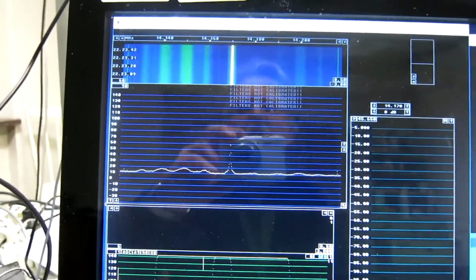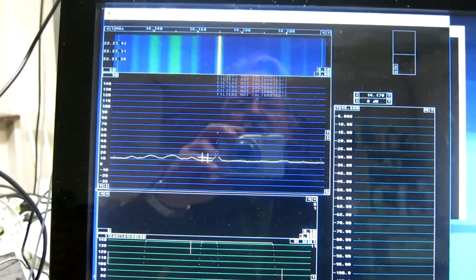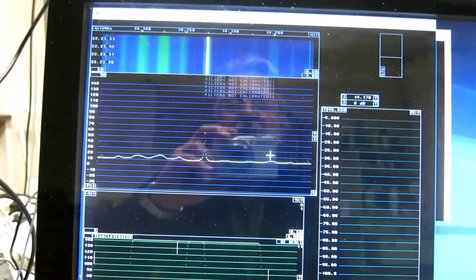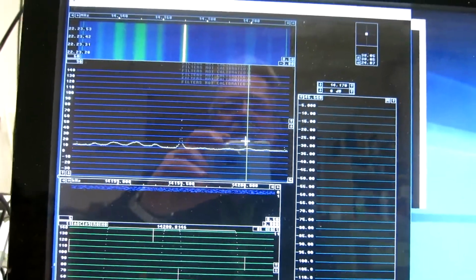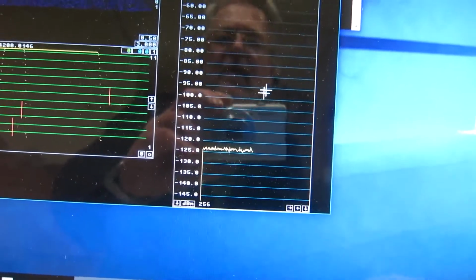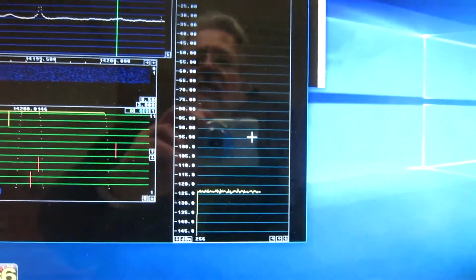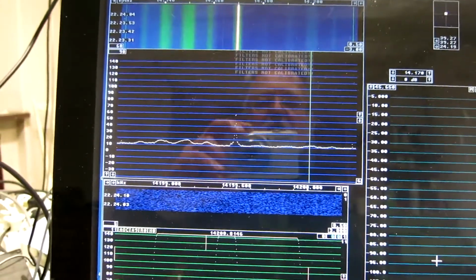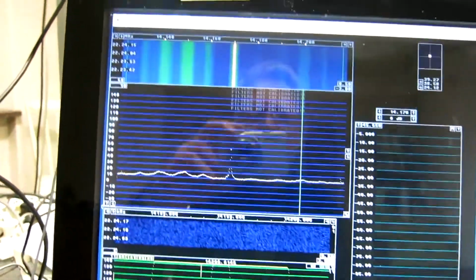The noise floor is not symmetric with respect to the center, so I think fair might be to pick a frequency like here, for example. Not the best one, but not the worst one either. And to say that this card is something like about minus 124 dBm, with better and worse positions on the spectrum. Now, there is something very special with this card.